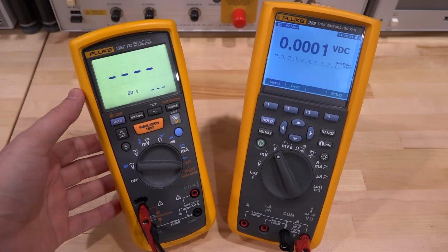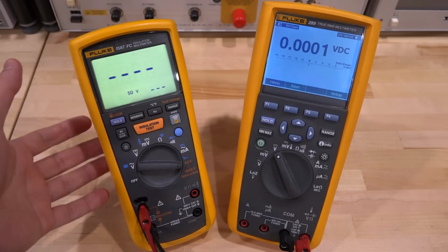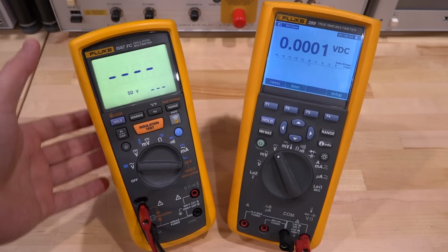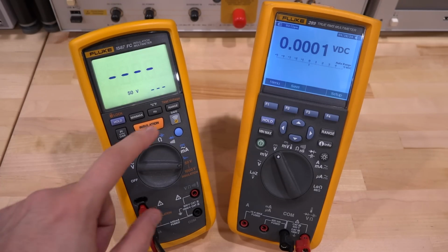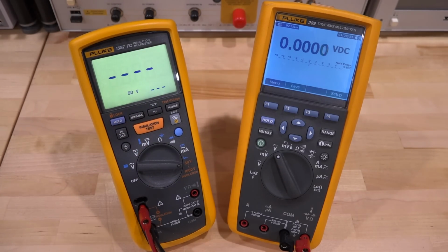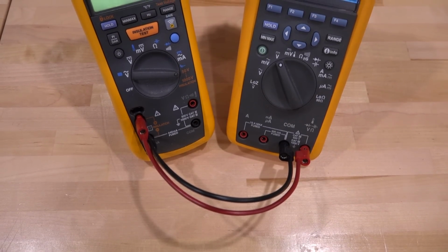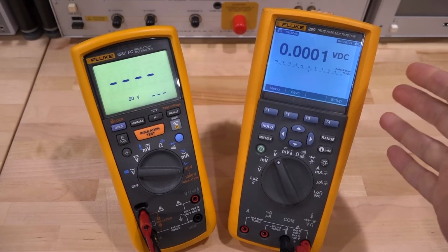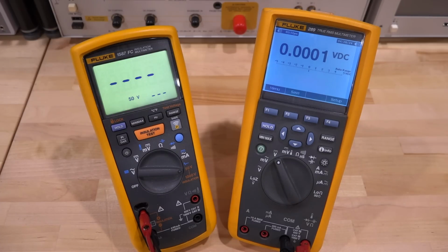And then you can measure the current through some unknown load, and it can tell you how good the insulation is, up to hundreds of mega ohm, which would be difficult to measure with a lower source voltage. So right now I have set it to 50 volts, and I've connected the two inputs together like this. We're just going to use this Fluke 289 both as a multimeter but also as a load because it has an input impedance of 10 mega ohm.